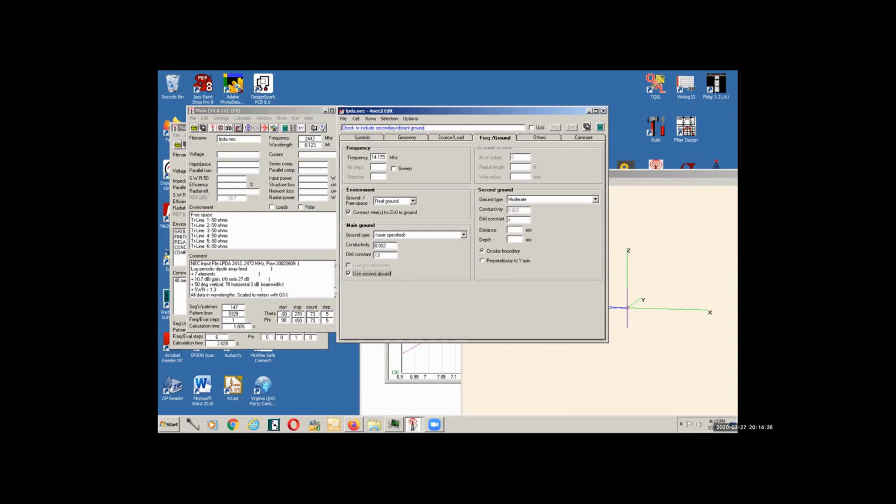Oh, nice. I do have one more question, quick. I think you've answered this in a way. You said I don't think you can measure the transmission line effects, but suppose you had an end-fed antenna and you're modeling the VSWR, which would certainly depend upon having a proper 9-to-1 balun. I mean, that's part of the art of designing end-feds. Well, there actually is a way of doing that in NEC. Good question. It has the capability of doing transformers.